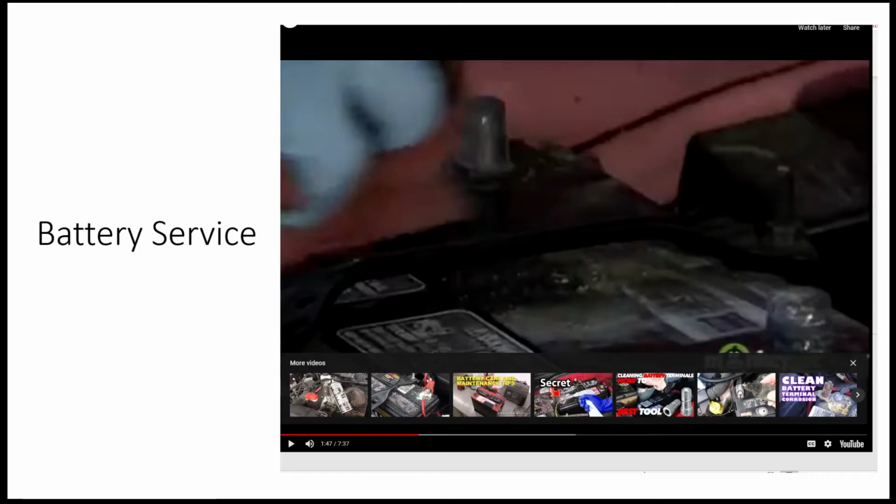There's a way to dilute this, and he should have at this point had a mixture of baking soda and water, poured it on, and diluted all of the acids. Very first thing, he should have diluted all the acids and prepared to wash the battery down with water, okay? Unacceptable, so be cautious of that.